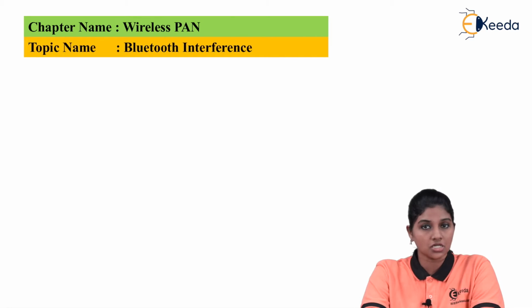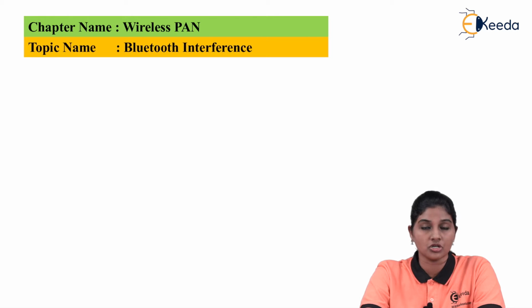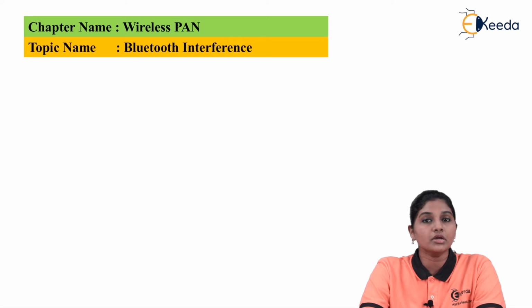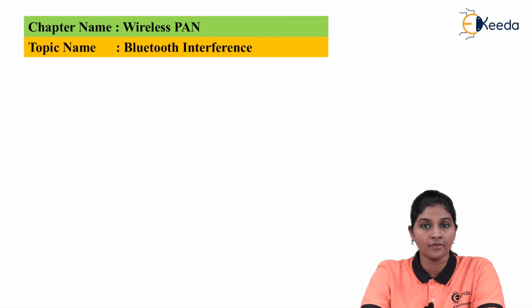Bluetooth is a wireless technology or wireless standard used for implementing the personal area network. As the name indicates, a personal area network requires covering a very short range, and therefore Bluetooth satisfies this requirement. Bluetooth typically covers a range of 10 meters up to 100 meters and provides a data transfer rate of 760 kbps, which can be extended up to a maximum of 1 Mbps.